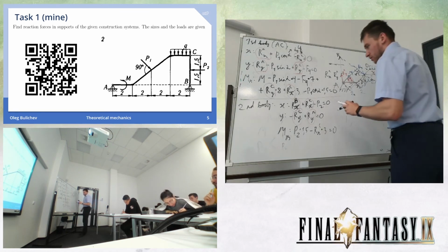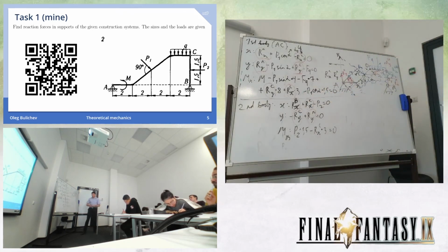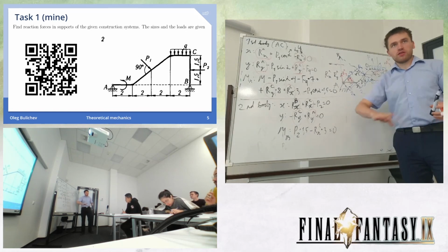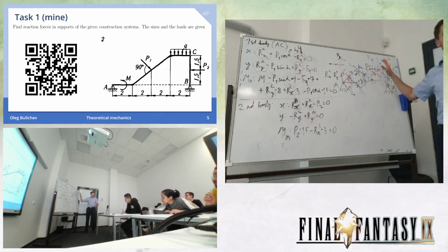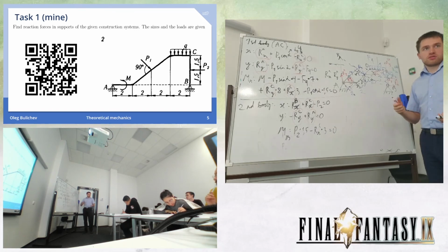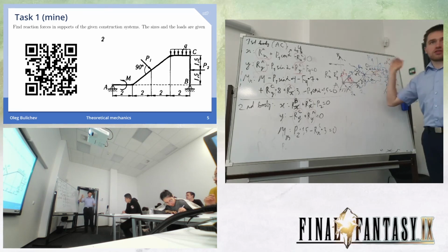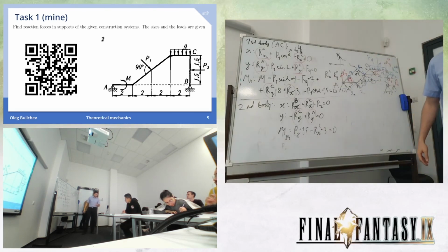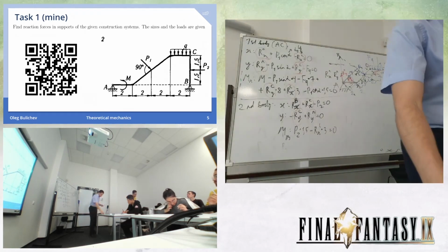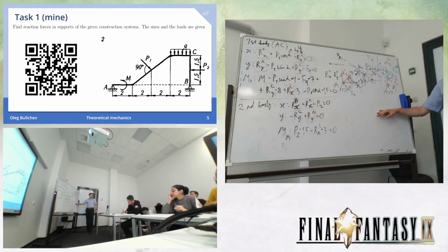So we have 6 equations and 6 unknowns, again only P2. Now, no P1, no anything, because we isolated. Actually, more dynamics works like this. For instance, the Newton-Euler method, which is widely used in robotic simulators, you are trying to write full dynamics for each body, and after this, add constraints. It's complex. Lagrange works differently. I hope it's clear. Any questions?